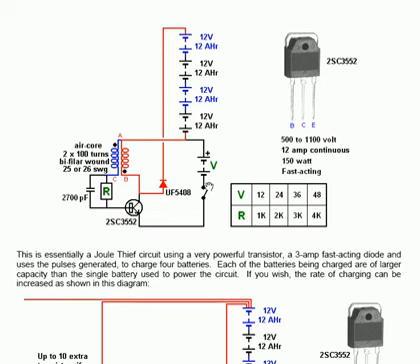This particular transistor he's chosen is a 2SC3552 transistor. That's a very powerful transistor indeed. It can handle anything from 500 to 1100 volts. It carries 12 amps continuously. It can dissipate 150 watts, provided obviously it has a heatsink, and it's also very fast acting. It's a very well liked professional transistor, that is, a transistor which is favored by professional designers for manufacturers.